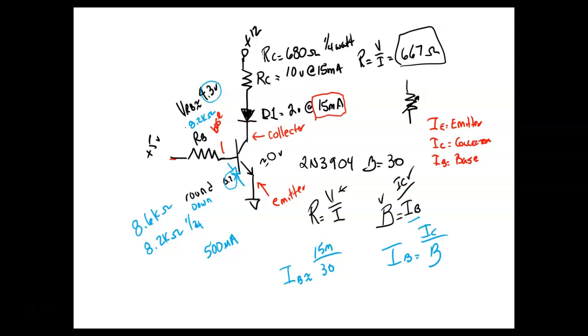Now they have a function, which is what Janet says. We have a function, limiting current in a circuit, but the work they do is create heat. These guys right here use that same feature that you learned in DC, but now we're controlling things with them. So we've got this bipolar transistor. We can use resistors to bias it and make it work the way we want. A bias does not mean you're biased towards something, but in electronics, bias means a DC voltage that you apply to a solid state device to control how it operates. It's its operating parameter.